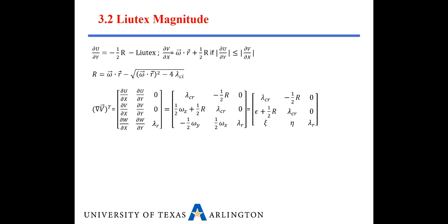Why? Because you have partial U, partial Y. You only use partial U, partial Y. When you add partial V, partial X plus anything, it doesn't change the vorticity, or it doesn't change the vortex strength. It doesn't change because you only use the smallest, partial U, partial Y. When you add more, for example, this is -1 and this is 3.